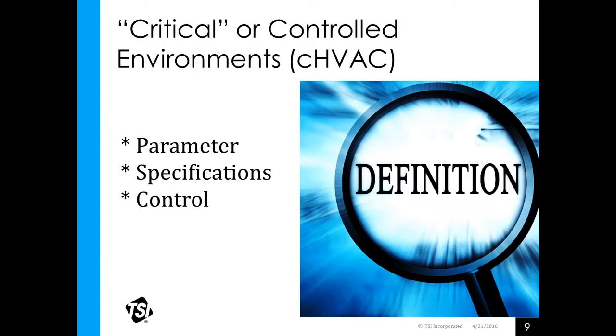We talk about parameters. The most common, obviously, is airflow. And a definition of HVAC, critical, residential, or otherwise, in my mind, is moving expensive air from point A to point B, arguably efficiently, double arguably affordably. So airflow movement is the first. The second parameter they all enjoy is pressure, and the only thing that moves air is pressure. So getting the proper pressure measurements is essential. I think number three is temperature.